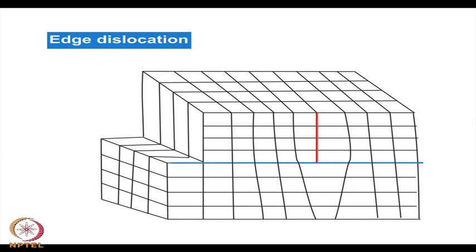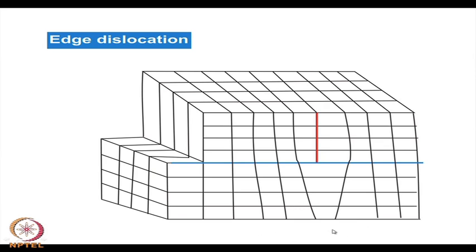So, finally, it may break. The whole of the top part will slip away from the bottom part, and one can say it has been cracked here. So, this part and this part have been separated, but before that there is an intermediate step, a transition region that is partly slipped and partly not slipped, partly deformed and partly not deformed. This is basically the concept of dislocation.